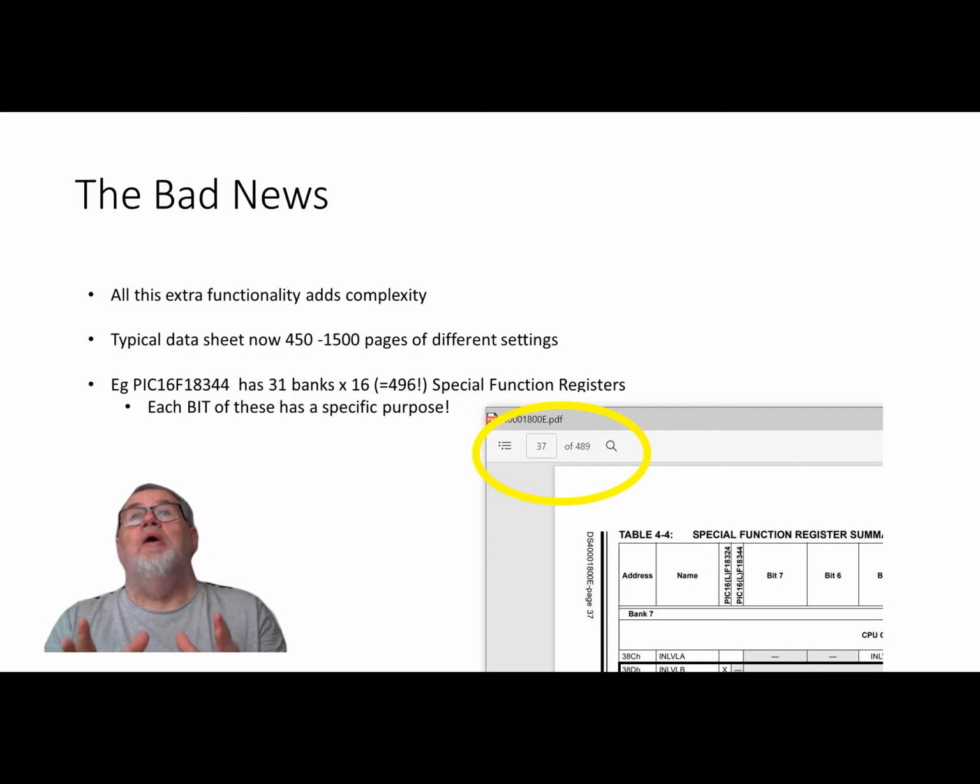And if you look at the way it works, a 675 has got 2 banks of special function registers, bank 0 and bank 1, and you change a bit, and that changes whether you're looking at those special function registers or those special function registers. Modern chips might have 32 banks or 64 banks of special function registers. So you have to pick which of the 64 banks of registers you're going to alter before you start altering it. It really gets complicated.